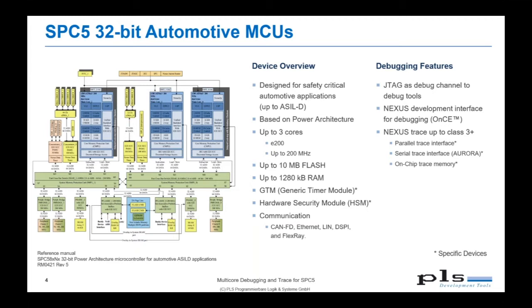On some devices, we also find a Nexus Class 3 Plus implementation. That means such devices provide program and also data trace. The trace can be recorded either into an internal on-chip memory, or it can be transferred off-chip at runtime using a parallel or a serial trace interface.